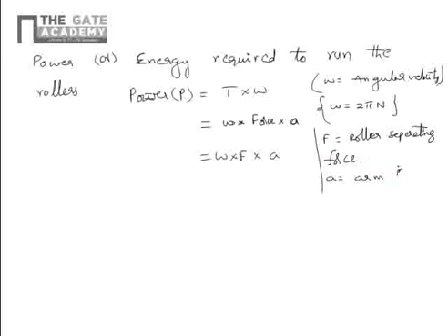A is the moment arm. A equals lambda L. Lambda is a constant which is called the arm factor. They will give the constant value for each material, varying from 0.3 to 0.4. L is the length of the deformation zone.